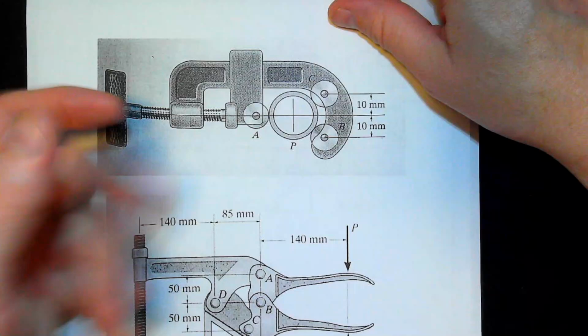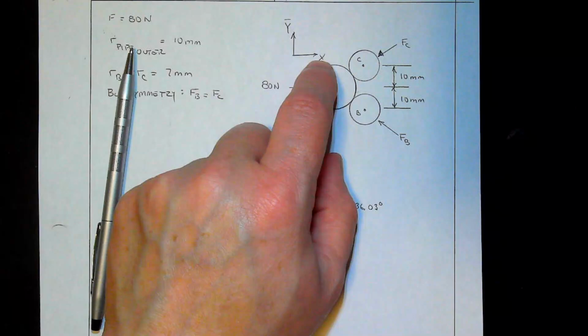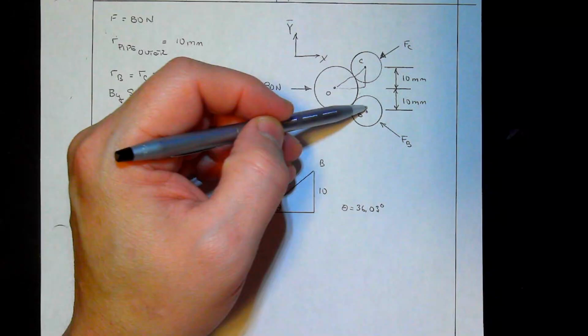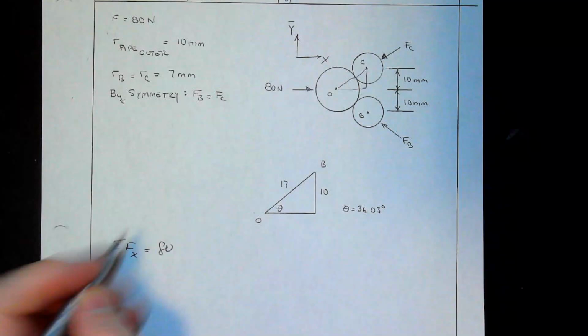All right, now we have AC. If we look at the vertical portion that's coming down, and then that horizontal distance, that'll be going counterclockwise. So that'll be plus FAC sine 60 times 0.25 for the separation or horizontal distance. Now if we take the horizontal portion going across here, and that's 1 foot away, that again would go counterclockwise. So we have plus FAC cos 60 times 1.